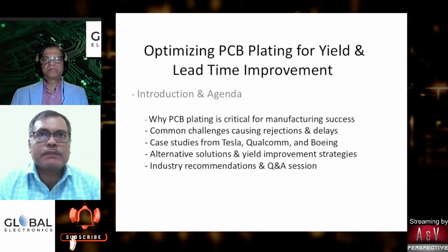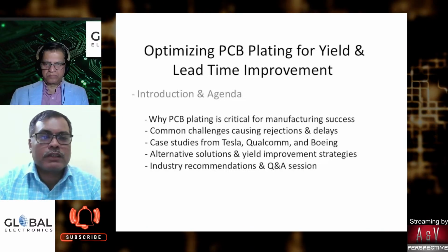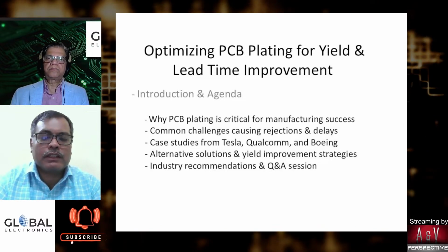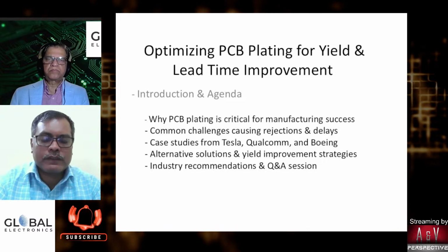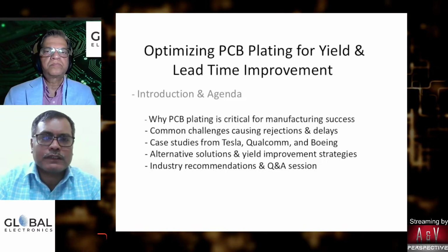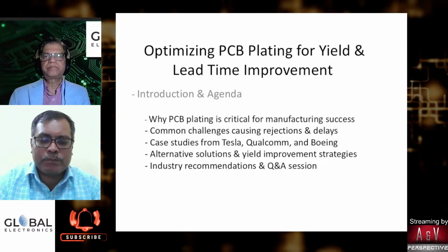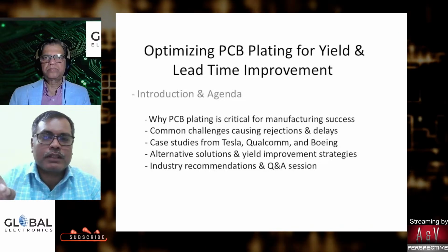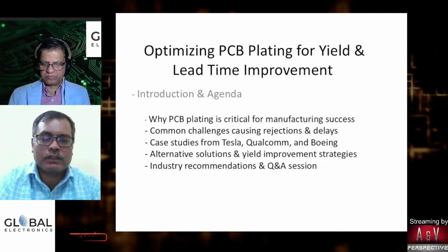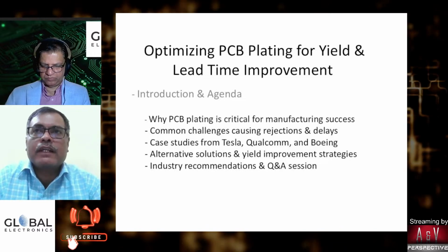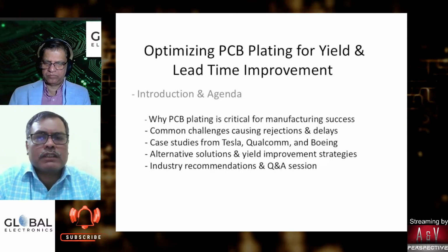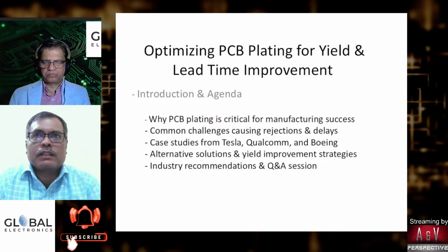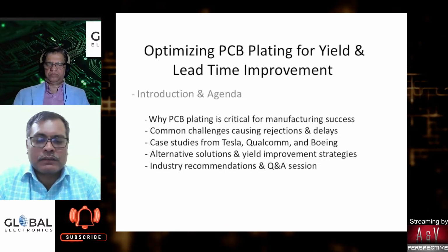So nowadays PCB size is reducing, so warpage of a PCB plays a very important role in the manufacturing, because the components nowadays are getting smaller and smaller. Like 0.5 by 1 mm pad components, if we are assembling in our SMT facility, then warpage is absolutely not acceptable. So that is one thing about the initial thermal management.